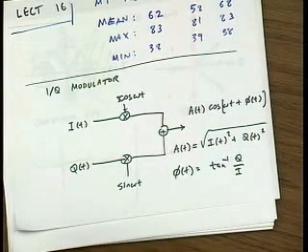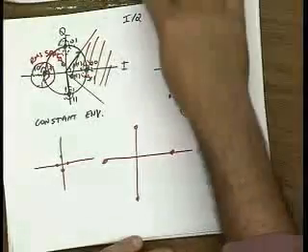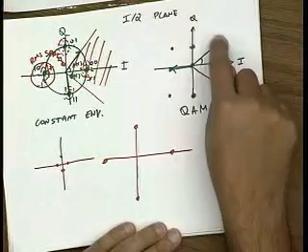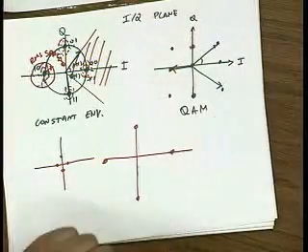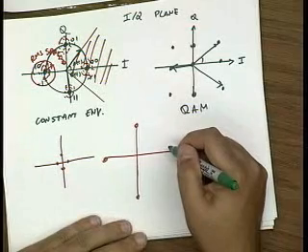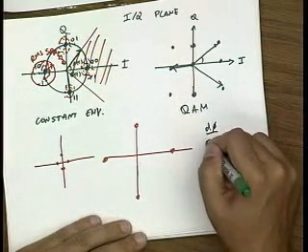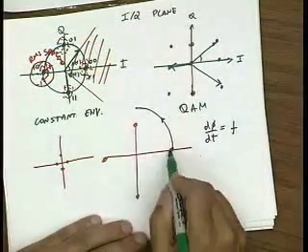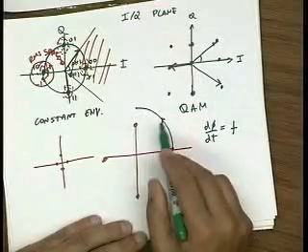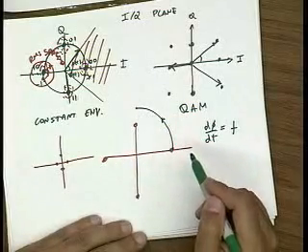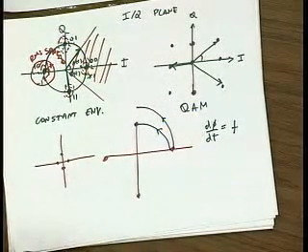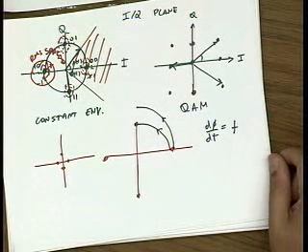Yes? Can you elaborate on the frequency modulation on this diagram? Sure. So basically, if I constantly change my phase, so if instead of sending discrete points, I send motion right along this circle, that corresponds to frequency modulation, right? So if I take d phi dt, if I move constantly along this point, that corresponds to frequency 1. So it's the rate at which I change the phase, which is the frequency. If I move faster, that corresponds to a higher frequency. Okay, good question. Any other questions?